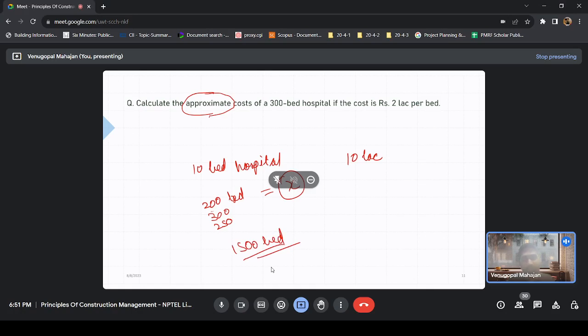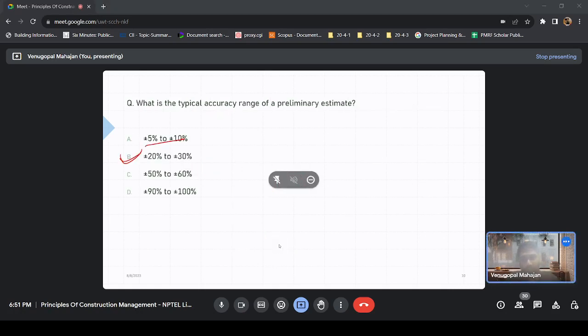So when you're talking about parametric estimating, the values have to be in the range, comparable. Like if you have to calculate the house construction cost, a hostel in IIT Delhi and a bungalow just outside IIT Delhi in South Delhi, you won't be taking the same parameters, same plinth area rate. Yeah, it will differ. So hopefully we'll keep this in mind.